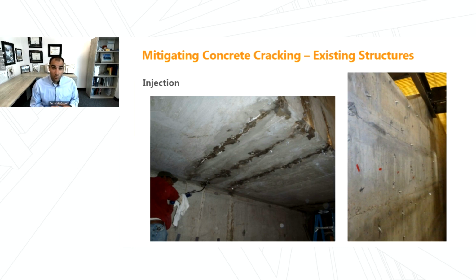And that urethane grout works by penetrating into the crack, expanding, and then sealing up that crack to mitigate water leakage through the crack. The advantage of that is that it can be done discreetly. You can address a few different cracks, but you need to understand why, right? You aren't going to use urethane grout if you have a structural concern or if you have large voids or honeycombing in the wall. That's not going to be as effective of an approach.